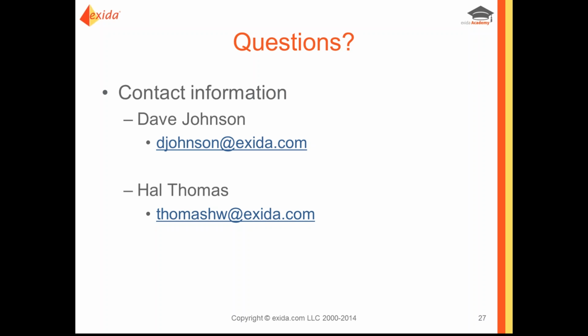For instance, over a period of time, perhaps you will get components, let's say semiconductors, other components within the system that could potentially fail. So as a part of your design and making your equipment hardened, you want to make sure that your system is designed with high reliability components. So any potential failure of those components would be what's known as a random failure.